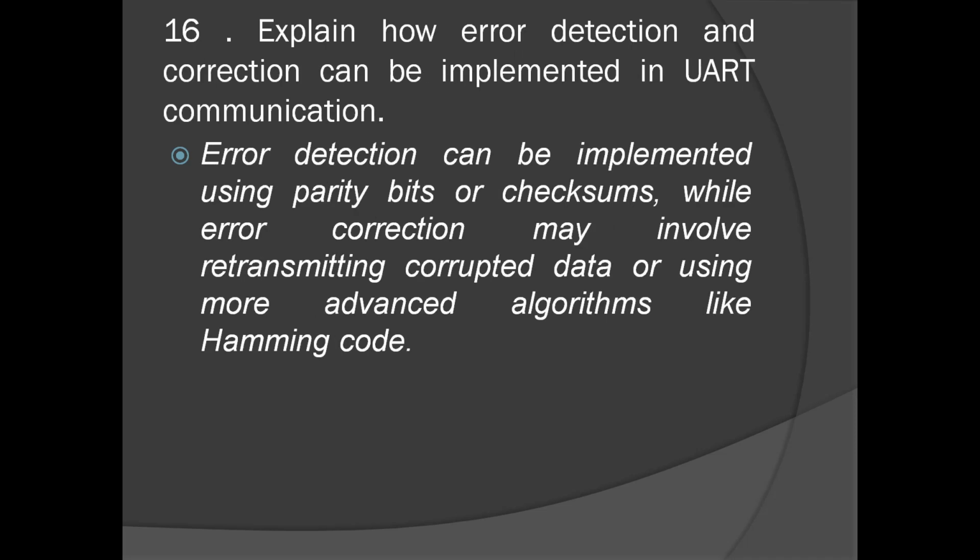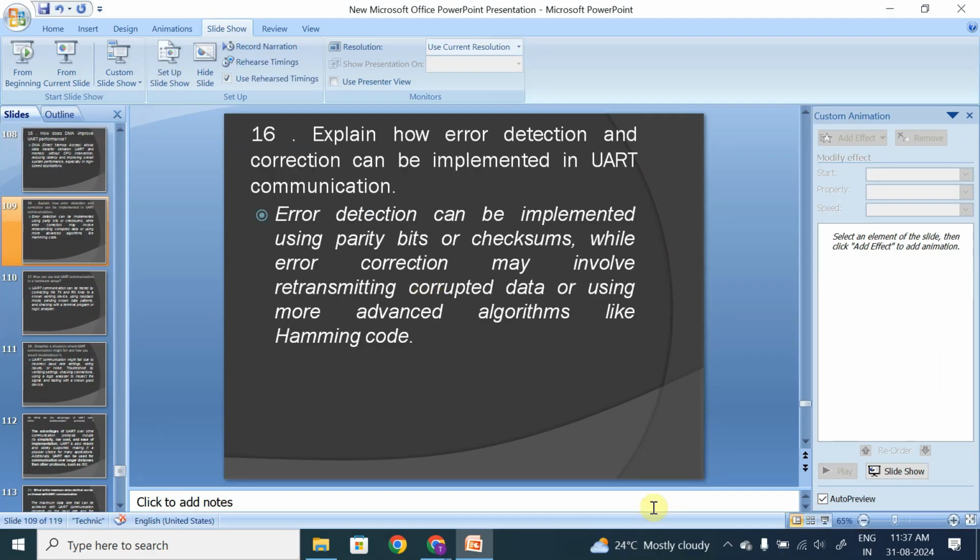Okay. I'm saying a simple example. If you have in hand a UART module or UART hardware device, you can connect it to some CPU, or end to end, right? And you can connect the transmitter line of that UART to the receiver line, and by sending data from the transmitter line, you can check it in the receiver line. Okay. Is this clear? For example, I will show one UART module. Wait a minute, let me pause the recording.